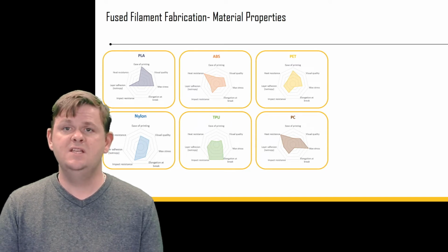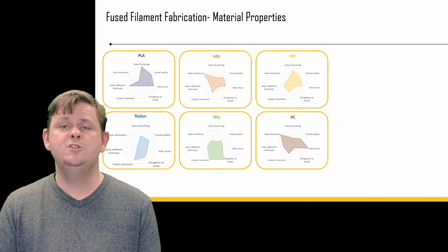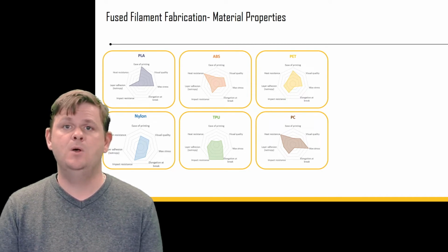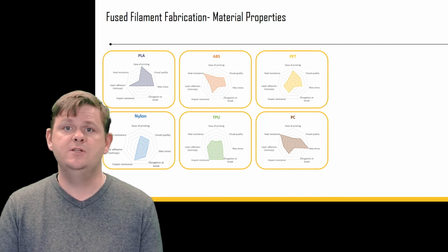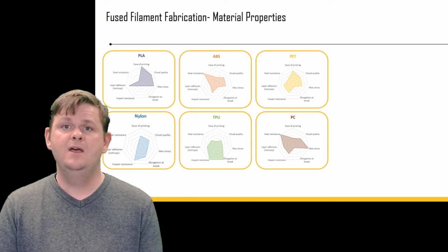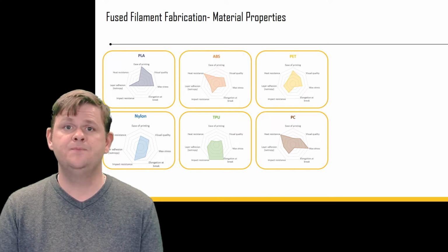We also need to consider materials before we print our part for repair. Although there are hundreds of polymers to choose from, including composites, they generally fall into the 6 base polymers. PLA prints well with good layer adhesion and visual quality. ABS is very heat resistant. PET combines good overall durability with ease of print. It can also withstand dampness.